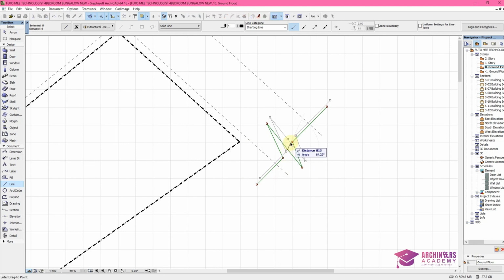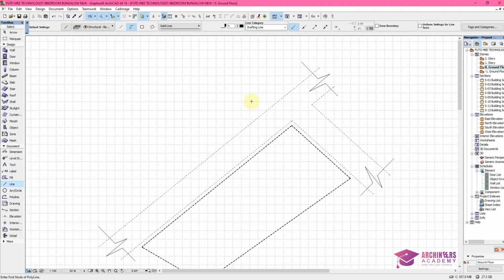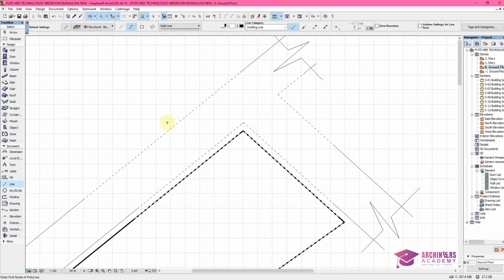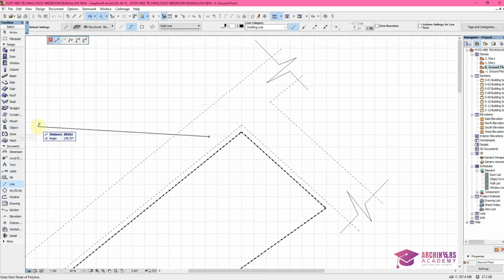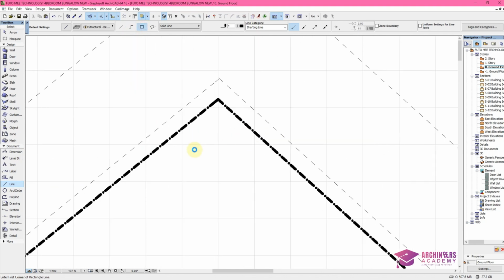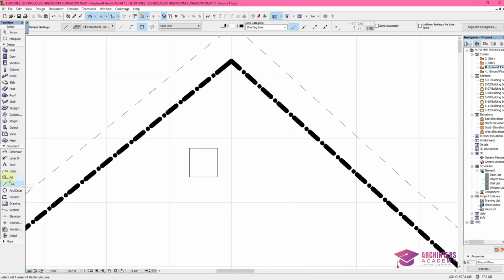Alright, so you can also insert boundaries. You can insert boundaries by coming to line again, making a box of around, let's say, 900 by 900, then maybe making a circle in the box too, of 450 radius, so it can lap perfectly on the box.